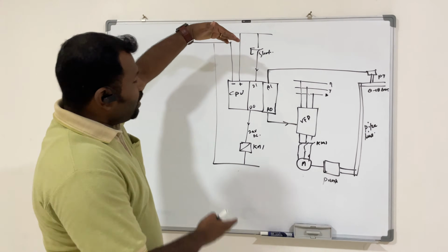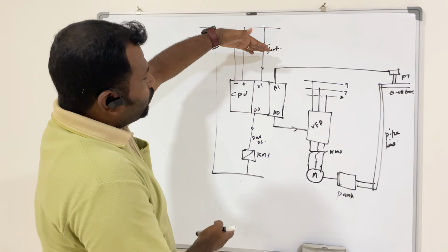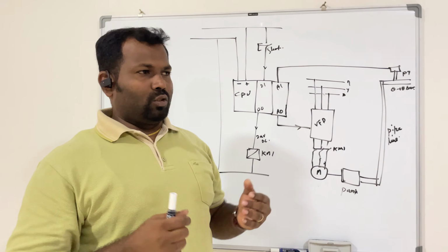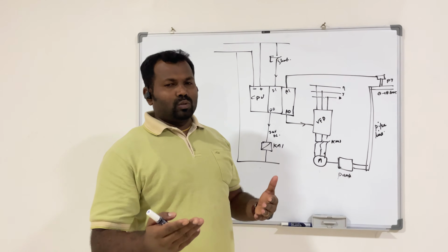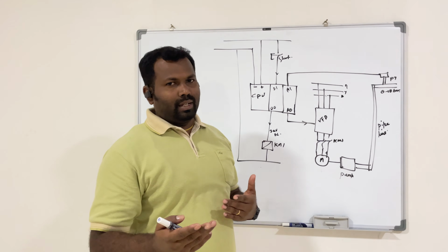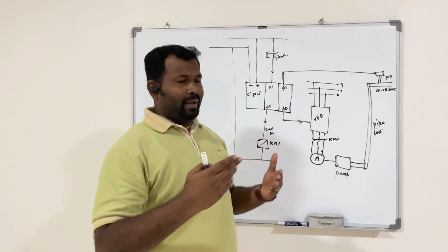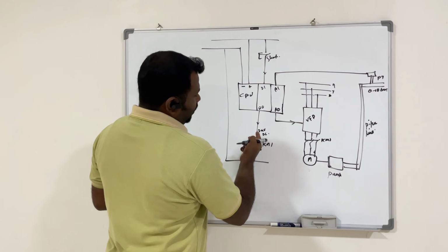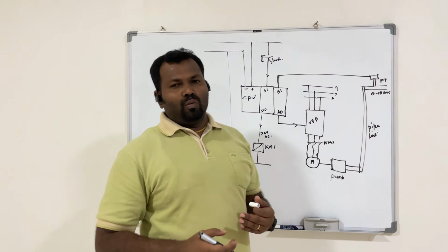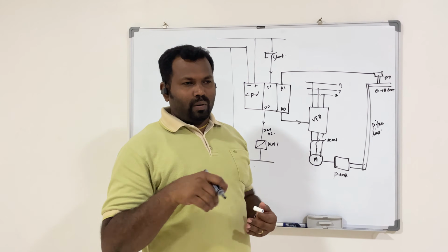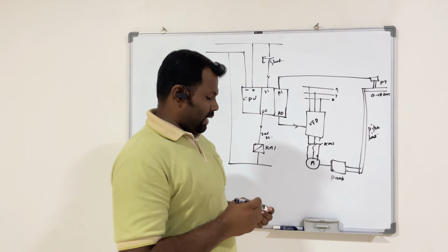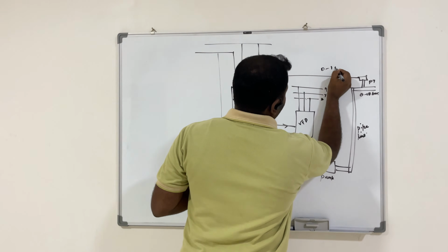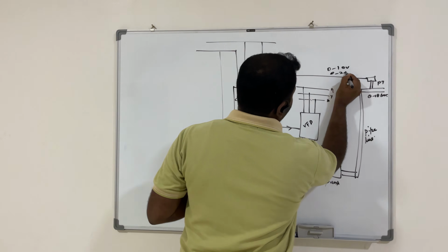This digital input or output could be any voltage. Commonly this PLC works with 24 volt DC, but some small PLCs work with 230 volt, as per the PLC manufacturer. Digital output also could be 24 volt DC or a volt-free contact. Through this volt-free contact you can connect your available voltage. But an analog input could be 0 to 10 volt or 0 to 20 milliampere.